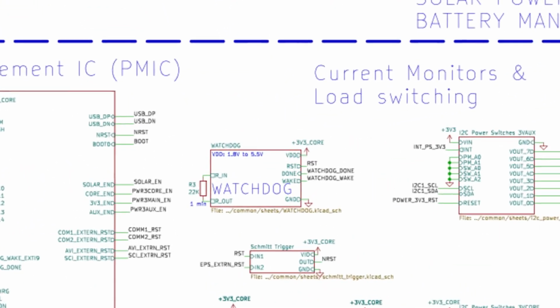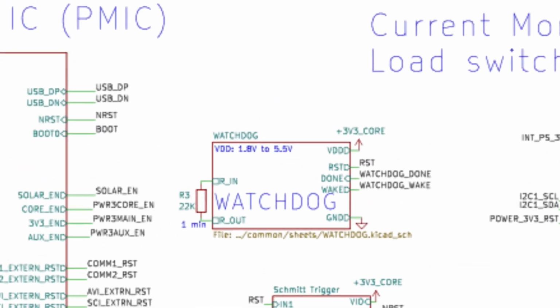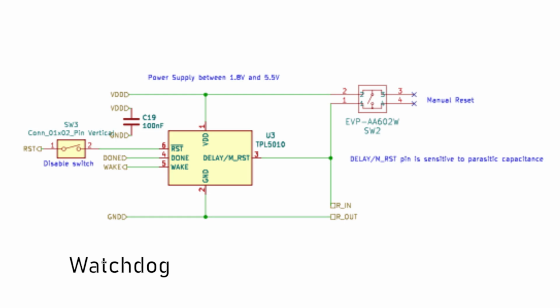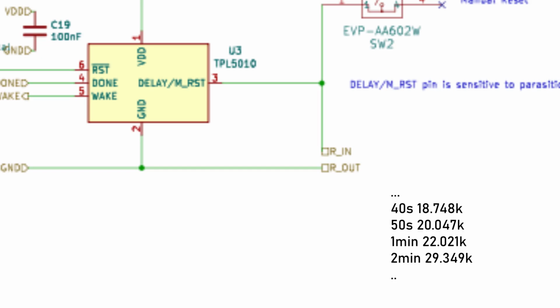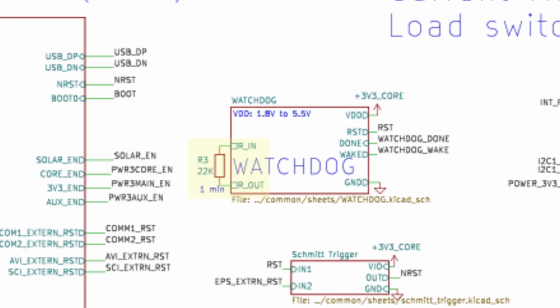CubeStack boards run unattended. If something locks up, I need a guaranteed recovery path. This sheet handles external watchdog timing, a wake-up signal that must be acknowledged, and it resets the MCU if that signal isn't acknowledged in time. Here's our customization trick. The wake-up interval is set by a resistor. To give each board its own interval if necessary, that resistor sits outside the sheet, connected through hierarchical labels.